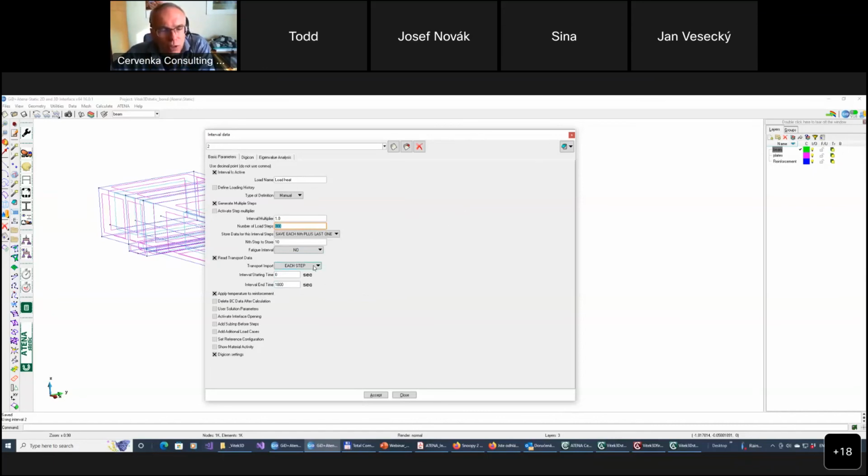There is also this option that either I do it at the interval beginning. This means it will extract this whole interval. So imagine at some point, the temperature increases at one single point from 0 to maybe 1000 degrees. So this information is extracted, this 1000 degrees. And now because here it is defined 300, I divide this 1000 into 300 steps, and they are gradually applied.